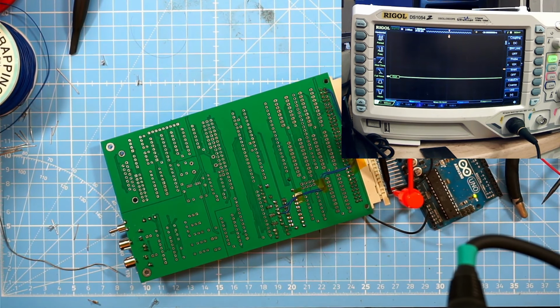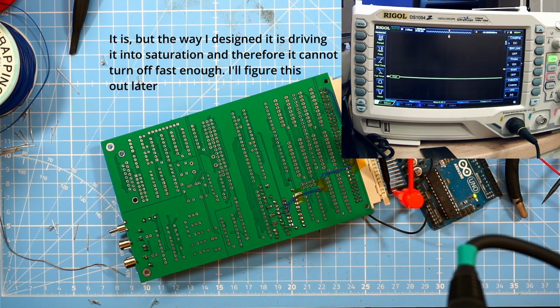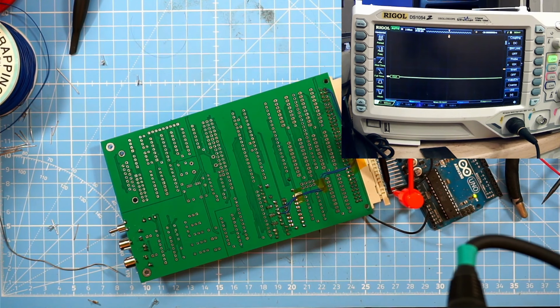So I thought that the 2N3904 would be capable of switching frequencies up to 100 megahertz. At least that's what I read in the datasheet. Datasheet's right here. Transition frequency 300 megahertz, 10 milliamps, 100 megahertz. I'm not that experienced with this kind of stuff. As you might have guessed, you might already know the answer.